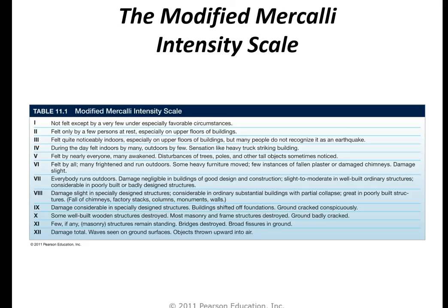So this goes from 1 to 12, and this is not the same as a magnitude that we talk about when we have a magnitude 6 earthquake. These are just different Mercalli intensity scales that talk about the destruction of buildings that would occur. From 1, not felt except for a very few under specially favorable circumstances, up to a 12, damage is total, waves seen on ground surfaces, objects thrown upward into the air.